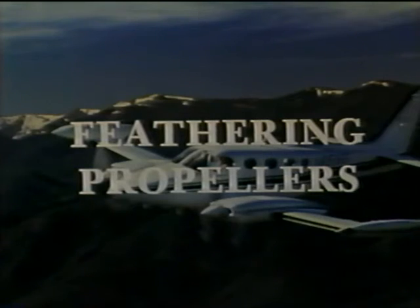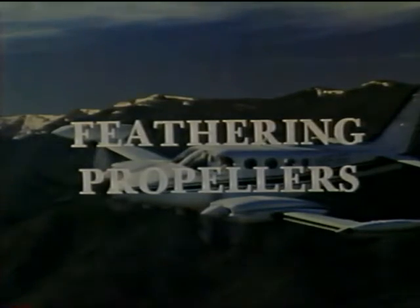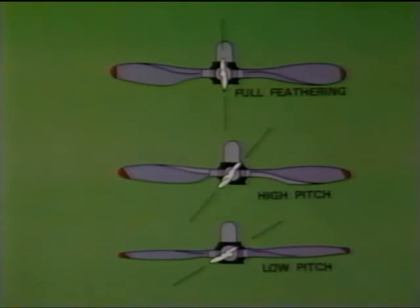Feathering propellers are used on all modern multi-engine aircraft. The primary purpose of a feathering system is to eliminate the drag created by a windmilling propeller when an engine fails. Feathering propeller systems are constant speed systems with the additional capability of feathering the propeller. This means that they have the ability to rotate the propeller blades to an approximate 90-degree blade angle.